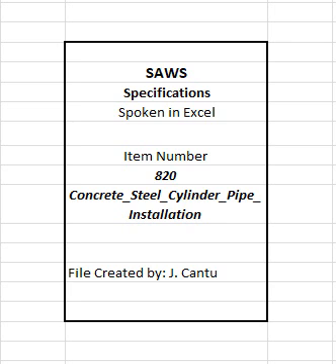6. American Water Works Association, AWWA. A. AWWA C206, Standard for Field Welding of Steel Water Pipe. B. AWWA C207, Standard for Steel Pipe Flanges for Waterworks Service, sizes 4 inches through 144 inches.